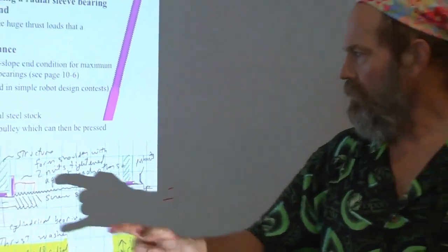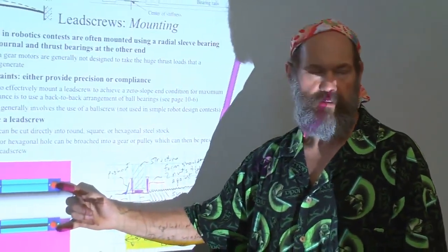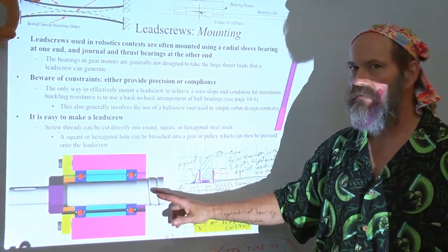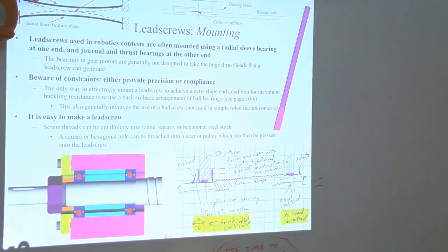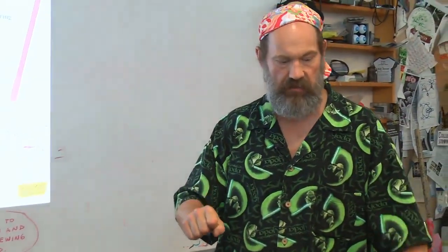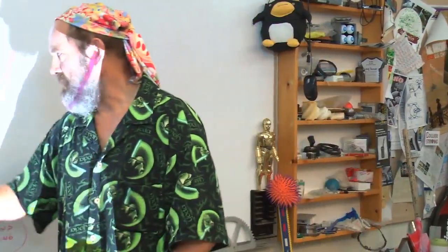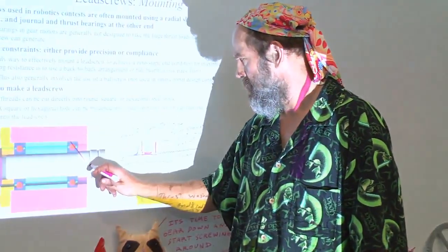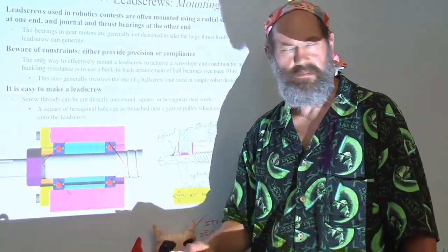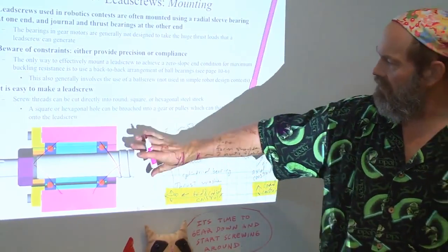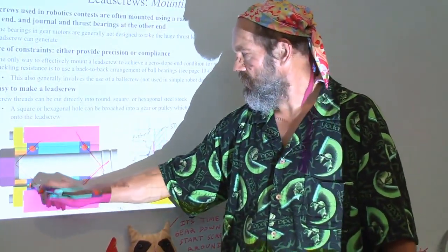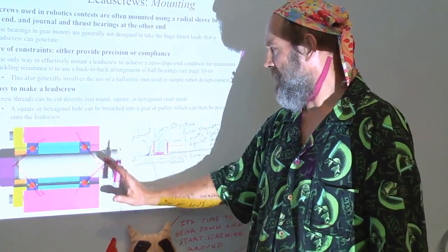How do you do that? Well, you need to make sure that your bearings are mounted such that they grab the shaft effectively by several shaft diameters. Remember the topic 3 fundamental principle, St. Venant's principle. If my screw shaft, and these are ball screw support bearings, and when we get into the topic on bearings, we'll talk about why these are these instant centers, the lines of action through the bearings, why they're like this, and why they're mounted back to back.